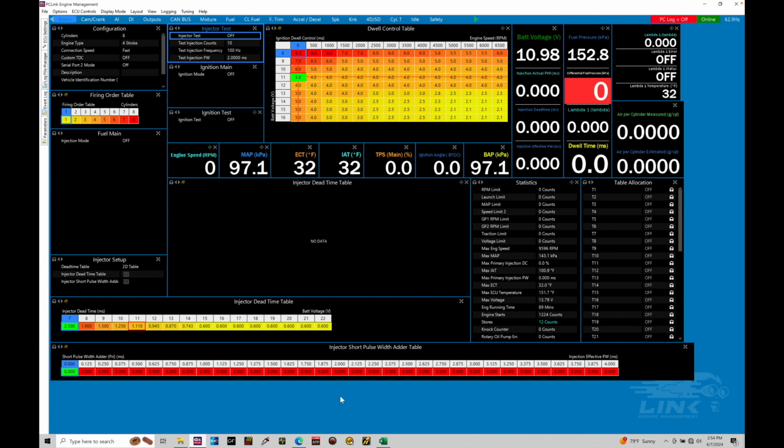We're going to be taking a look at working with temperature sensor inputs and programming for our Link G5 and G4X systems. In this tutorial, we're going to be specifically taking a look at setting up engine coolant temperature and intake air temperature. These are the two basic temperature sensor inputs we'll have for any installation on any engine. We may also find you're wiring in engine oil temperature, or even something like transmission or differential temperature. You can use other temperature sensor configuration and input setup with the Link. What we'll learn from setting up our engine coolant temp or intake air temp will apply to setting up any type of temperature sensor input in the programming. Very straightforward, so we're going to dig in here and learn how to do this.